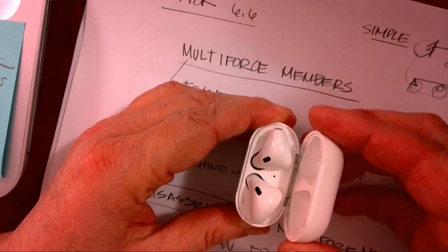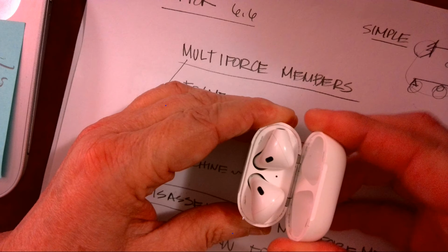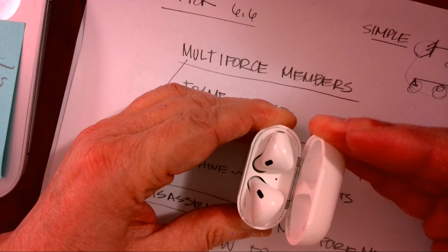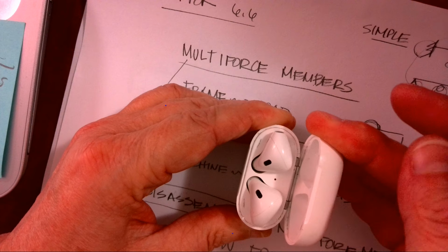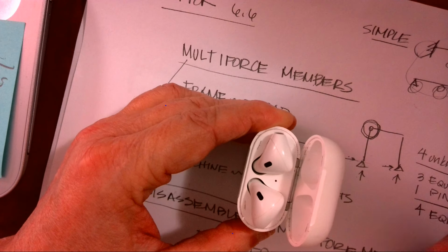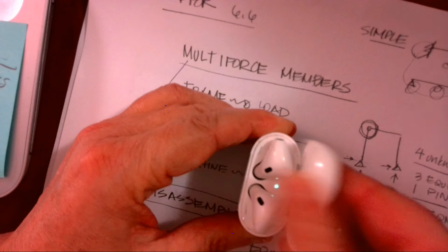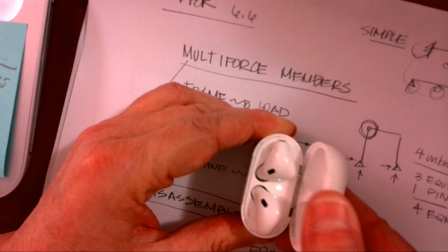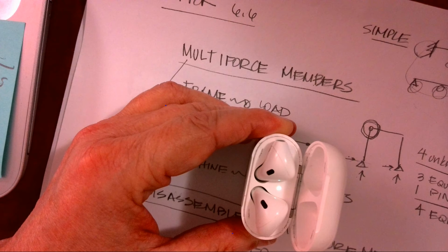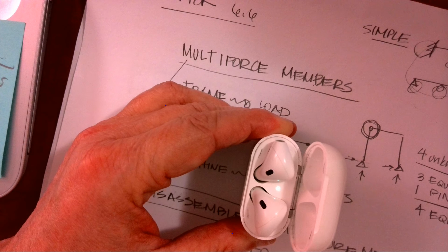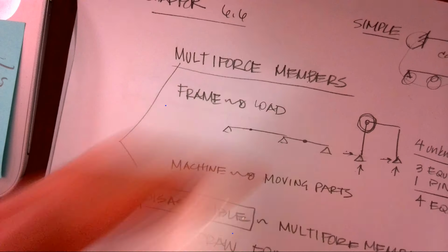Likewise, if I tried to move it in the Y direction, it's not going anywhere. Okay, so as I try to pull it towards me, see, my thumb is having to push back to keep it in place. This force is being transferred through the pin. So a pin can transfer X and Y forces. The second that I apply a force that causes rotation, rotation occurs. If we have rotation, we don't have a moment developing. Remember, forces only develop if we are resisting translation or resisting rotation. So that's a pin.